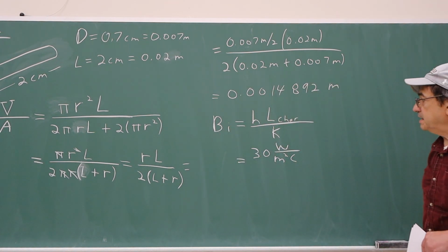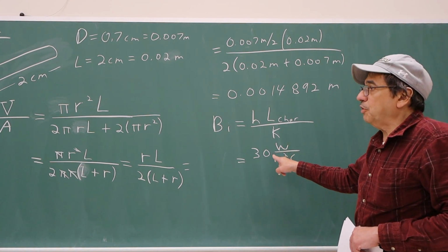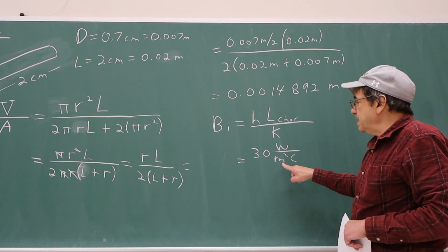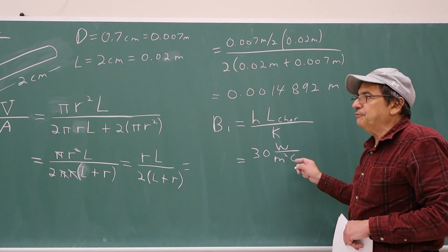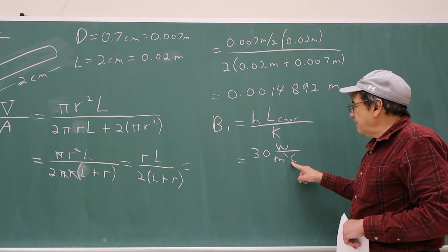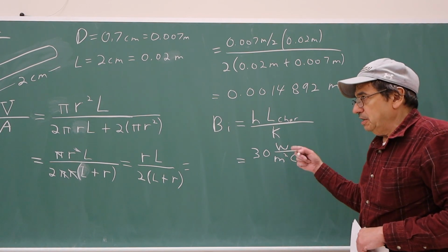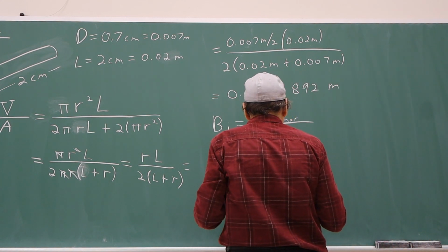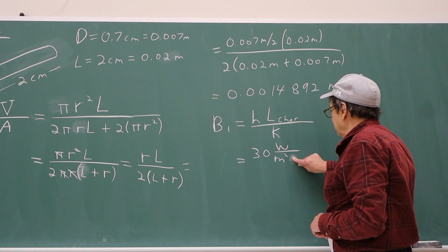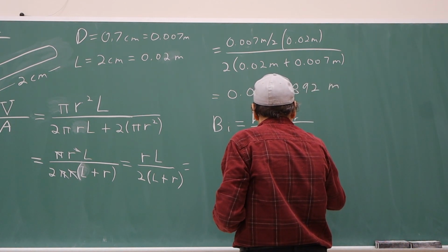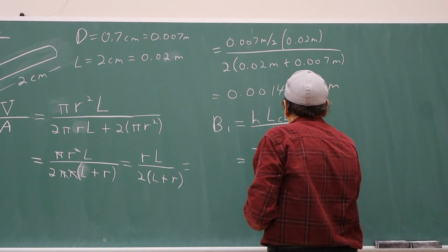degrees C. Now one thing you'll notice a lot of times, these heat transfer coefficients will be given like in meters squared C or meters squared K. Because we're dealing with differences in the temperature, you'll have the same value usually for if this is K or C, so you can interchange those. So actually the way it was given in the problem, we were given a K here for Kelvin. And again, the characteristic length we just calculated.